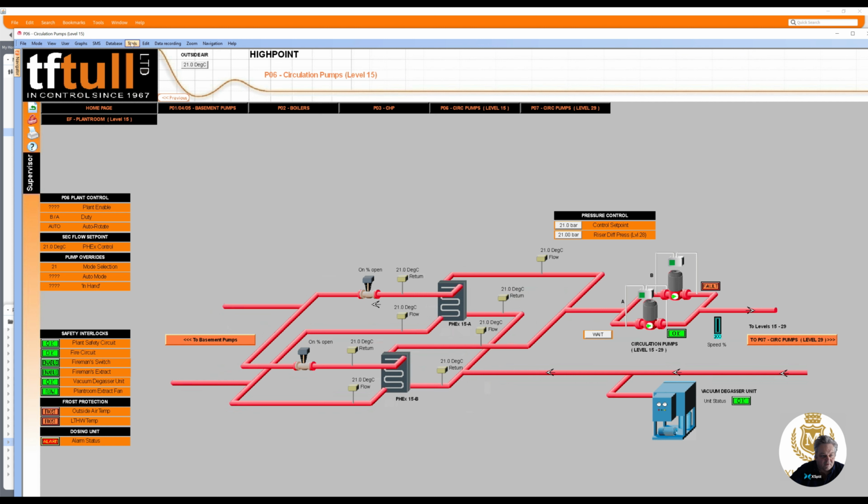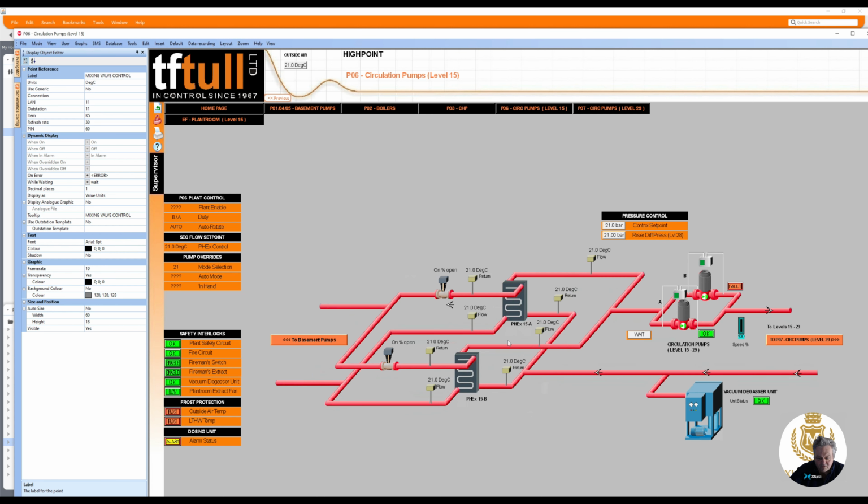So I will then go to edit, configure page, and then I will click on that, for example, and then I know that is LAN 11 outstation 13. It's the I9, but I know that when off we're okay. When on, so when it's true, we've got a fault. So I can tell from this what's a fault and what isn't a fault.